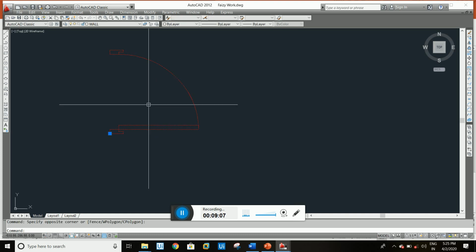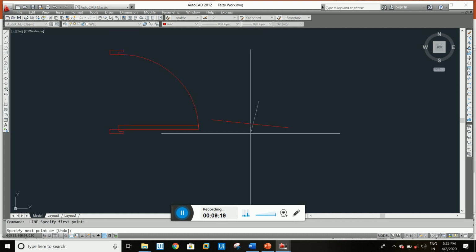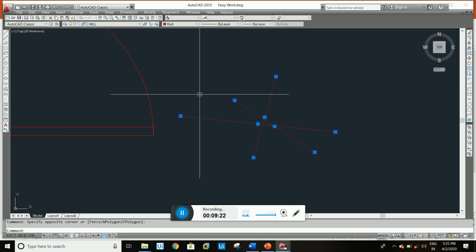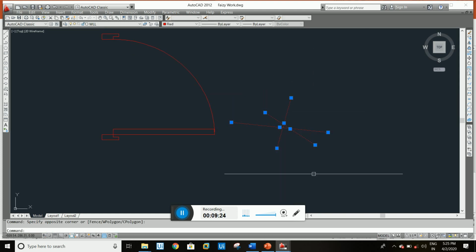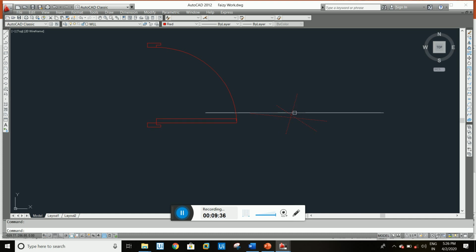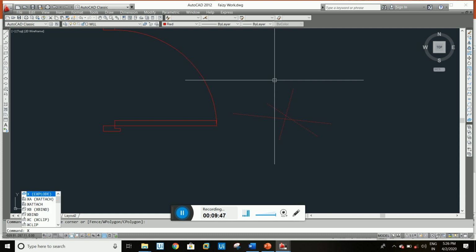This is now, guys, the block. A block makes objects into a single object. Like if you create a line, 1 line, 2 lines, 3 lines, these are different objects, and we want to make them one complete object, like grouping them. So we can use the block command B, give some name, and open. Now this comes as one object, and with the explode command we can explode it again to the previous position. If you select this object, press X on your keyboard and enter.